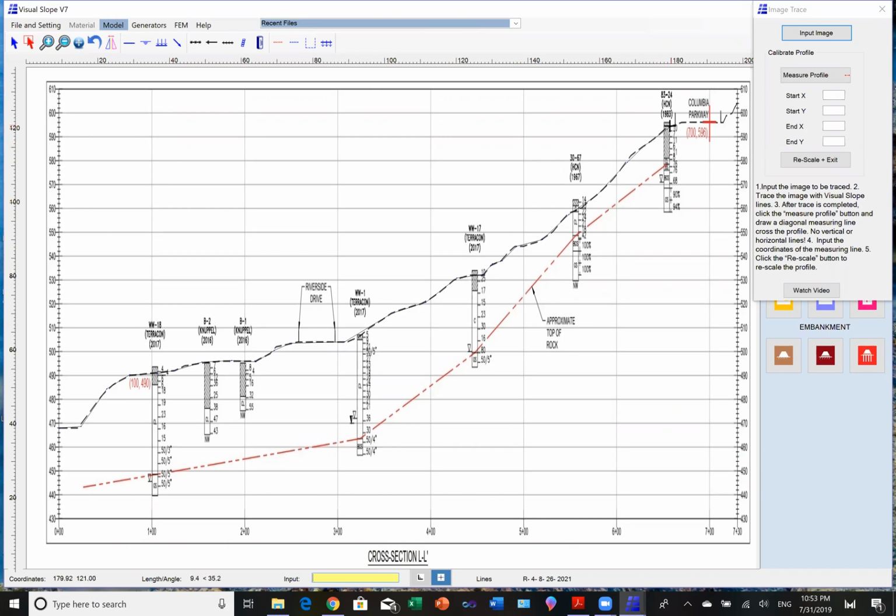And you can see this is the top of slope. It's very easy to just draw in. And we can do the same thing for the top of rock. Here is the top of rock. Someone says maybe this method is not that accurate. I would say it's pretty accurate because the top line is only measured from the field, and you pick up one cross section, and the survey may not actually use that section. And plus, if the slope only has like a 10 centimeter difference that will determine whether the slope is stable or failing, then this slope is not that stable anyway.